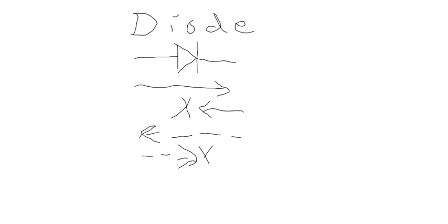Now, we have already been talking, in some videos I've asked you to watch, about what happens inside the diode and why the diode works like it does. A P-N junction is basically a diode. And when we do that, we do need to talk about electron current flow to understand it. So I will use electron current flow when I'm talking about what's going on inside of a component like this. But all other times I tend to use the conventional current flow model. I want you just to understand both of them. And a transistor works kind of the same way.